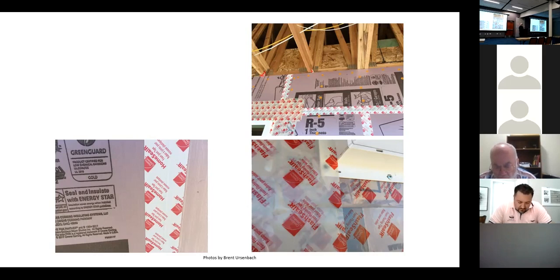I'd say 13 and 5. I agree with you. Because they're continuous. Because you have continuous insulation, you're eliminating some of that thermal bridging. We're actually seeing up in Canada and Alaska and colder areas that they're putting all the insulation in many cases on the exterior, 4 and 5 and 6 inches, and not doing anything in the cavities, because continuous insulation works so well and it solves all the condensation issues.